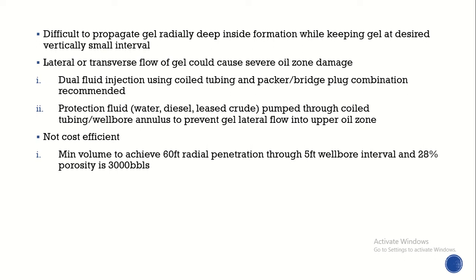For dual fluid injection, using a coil tubing and packer or bridge plug combination is recommended. A protection fluid, be it water, diesel, or crude, is pumped through the coil tubing to prevent the gel lateral flow into the upper oil zone.